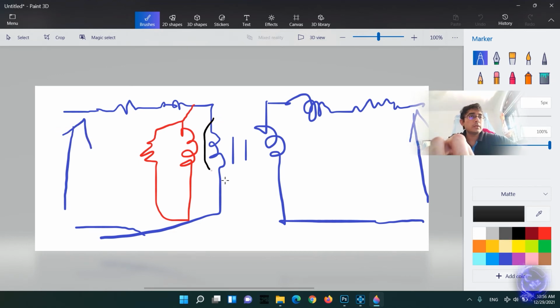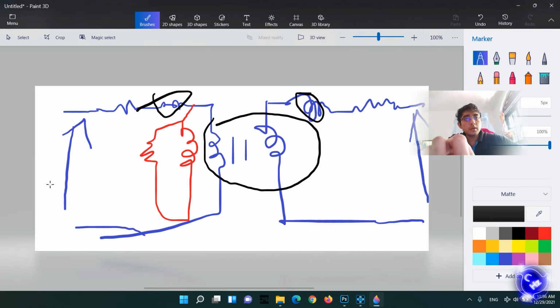Secondary leakage inductance and secondary winding resistance. So this is my secondary voltage, this is my primary voltage, this part is my ideal transformer. Right. So I am going to neglect the primary winding leakage inductance and the secondary winding leakage inductance. That means the mutual coupling between these two windings is perfect. Leakage is zero. It is a good approximation, no problem.